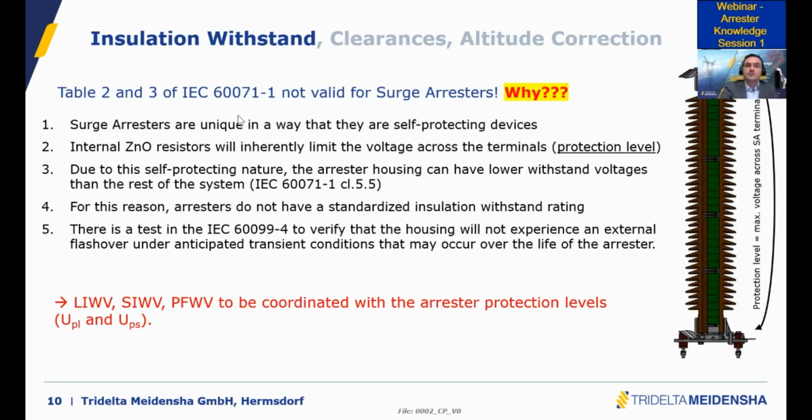You are calculating a security factor with that equation, right? And with that 8,150, with this factor, you are also involving the statistical behavior of the flashover. But this has been done before the surge arrestor standard was released, so this is not described. But sure, there was a scientific investigation before to find out which factor you have to apply for the statistical uncertainty. So yes, it's a constant number you have to consider in the altitude correction.